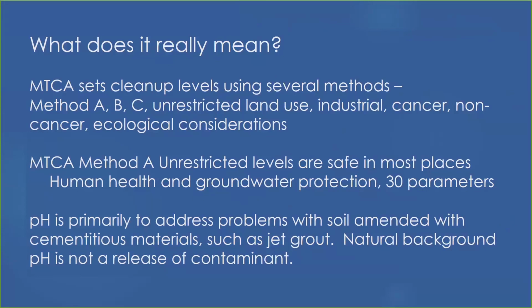And then the pH standard is going to primarily apply where you have done something to affect the pH of your soils. And so, engineered soils is something I keep mentioning. They have cementitious materials. These types of soils have resulted in pH of 11 or 12 or higher. That never lowers once exposed to environmental conditions, or it takes a really long time. And so what that can do is leach metals out of your soils, and we think that needs some safeguards if you're going to be placing that in the environment.